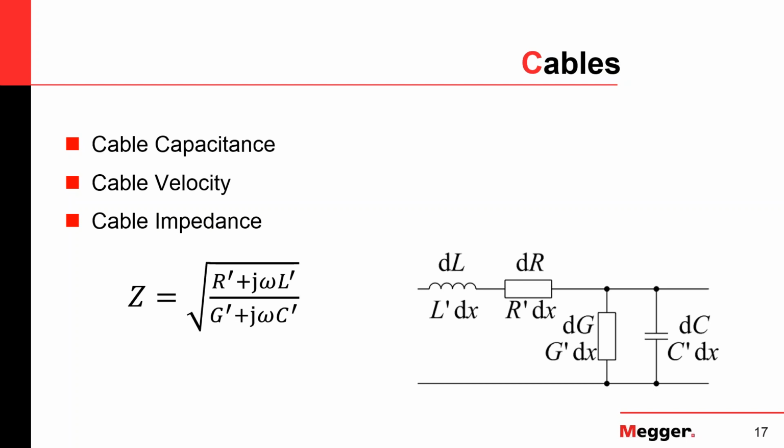And then we have the impedance. Now, don't be scared by the math in case you're not a math guy. This is pretty much important later for some of the prelocation methods. The impedance is determined by two things mainly. There's a material influence, which is the resistance.